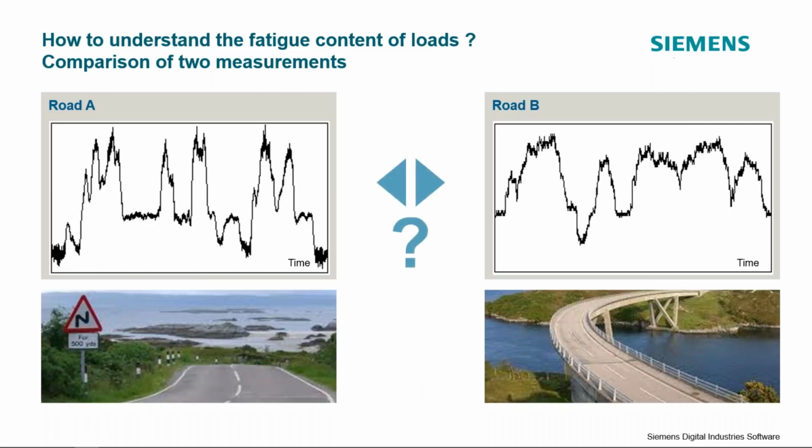However, in the real world, we usually don't have nice sine waves that we can compare. We have something more like this, where we have a variable amplitude loading environment. So our load is dynamically increasing, decreasing. There's maybe a dynamic component and a mean stress component.